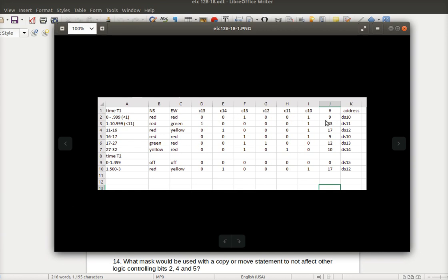What it'll do is take a number, convert it to the binary bits, and write it to the outputs. And when you're moving in Allen Bradley, you're actually moving a number to an output, and then the output card does all this breaking down that I had to set up for in the Click. So it's a little more powerful in the Allen Bradley.